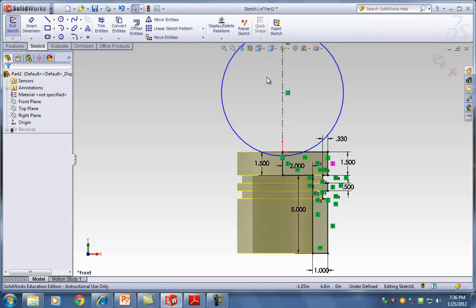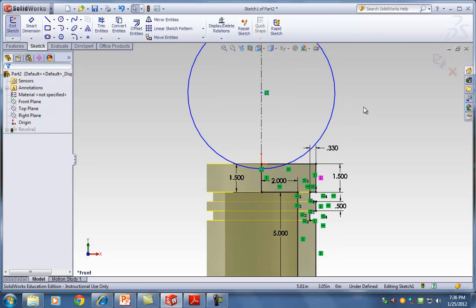How do you have the extrude or revolve thing with the circle line? Because when I do the extrude revolve, it drains out everything, so I can't do the circle. Yes. So what you do is you right click. I can't do it right now because my circle is still blue. You right click on revolve and you click on the second icon. It says edit sketch. That's how you go back into the sketch.